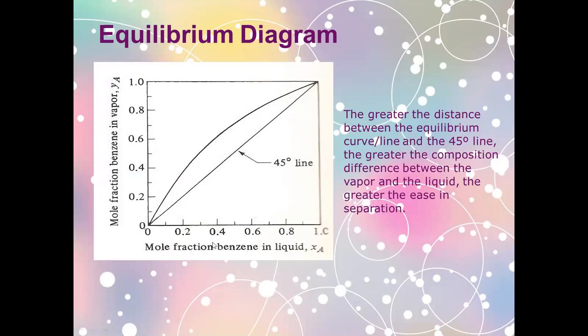And in this case, what you have in the graph is the relationship between the mole fraction in the liquid phase and mole fraction in the vapor phase. So for a particular system, when these two are plotted, referring to XA and YA, you will be forming this curve. Now, if the problem does not give a curve for a particular system, it is us who plot the curve.